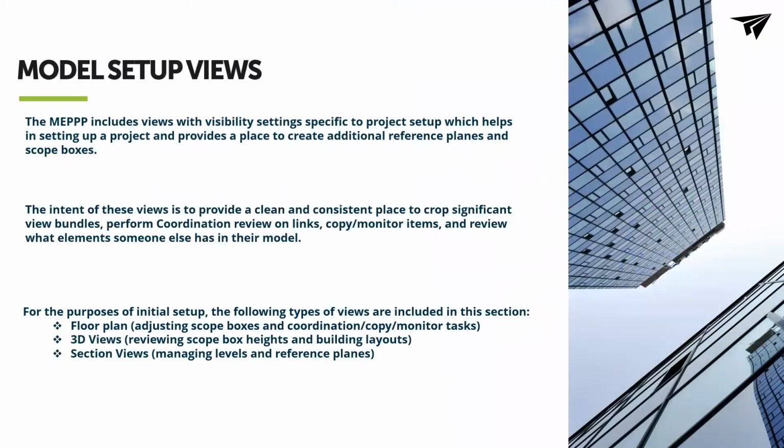Model setup views are the area where you're intended to actually bring in your links, set up your model, copy monitor, scope boxes, reviewing heights, managing the levels and the reference planes.